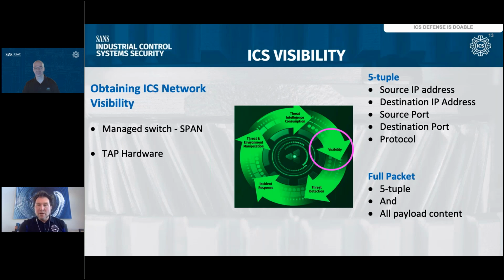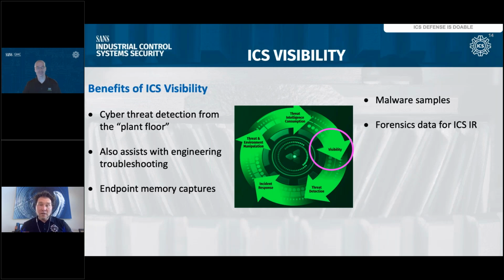Now, there are several benefits to network security monitoring and visibility in the ICS, looking at the network. What's important here, though, is you really want to go as deep as you can to get things like the communications at the lower levels of the Purdue model. So anything from level 0 to level 2, as an example, all the sensors and controller communication, and then from 2 to 3, you really want to get the HMI communications to the field and back as well. Critical. Also your engineering workstation, those critical assets, right?